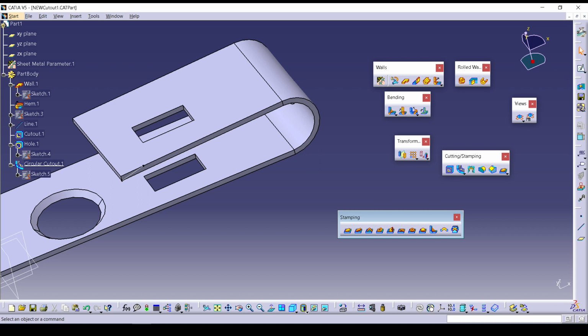You just have to click on the profile where you want. Here you will get the surface stamp, bead, curve stamp, flange cutout, lower bridge flange. This is pretty easy because it is a standard thing. If you give the right dimension, it should be perfect. And when you give an error dimension, it will show you an error pop up message.